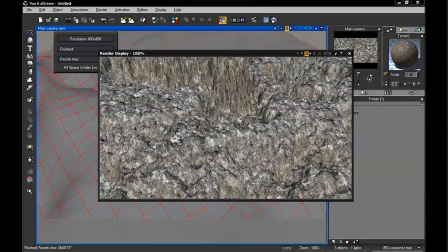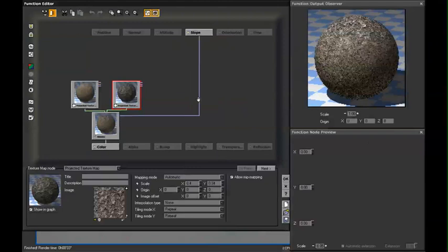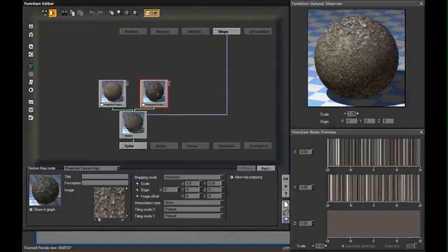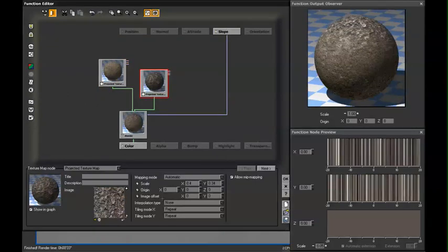We can see very nice looking texture on the tops and then on the sides of all the areas because it isn't as high of a degree. These are almost 90-degree slopes, very close, so we don't see as much of the texture. It doesn't look quite as good. So we can close that out, and let's just modify our mapping mode. And since our first one, this main material, is appearing on the flatter areas, we can actually change that to flat vertical, and it's not going to cause any problems.